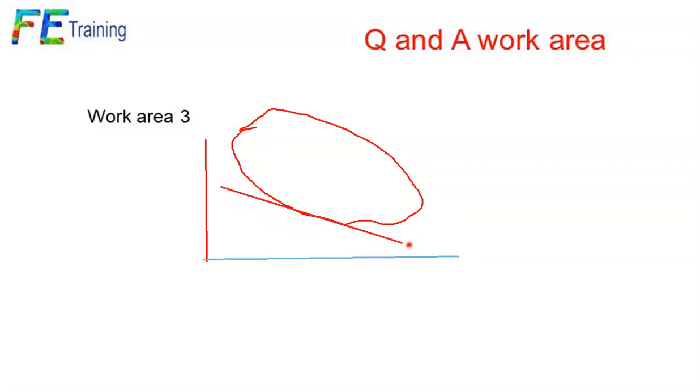So another way is to put a scatter factor on. The scatter factor is probably going to be at the high cycle fatigue end. We would be dropping this curve down to fit better. So again, we'd probably be using the endurance limit, or 10 to the 6 or 10 to the 7, to drop down in some way.